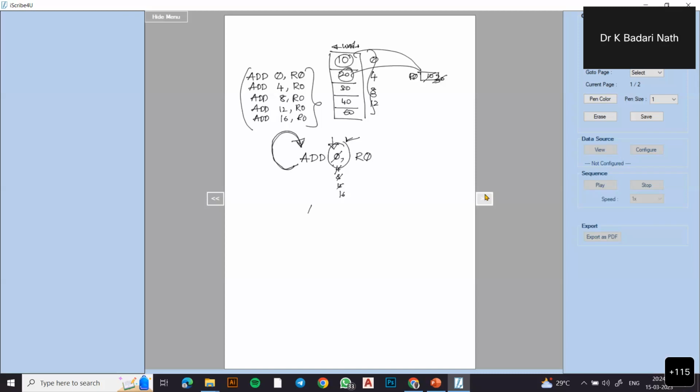Let's do that one now. Let's say add. Now I use an R0 register. If I just use R0, it is a normal value of the R0. Now I'll put a bracket here. So when I say bracket here, the meaning is different. So let's understand this now. I will use another register, because R0 I use for something else. Let's say add R1, comma R0 I specify.